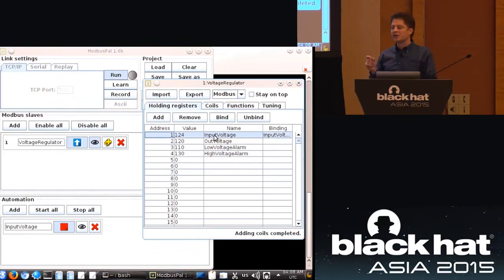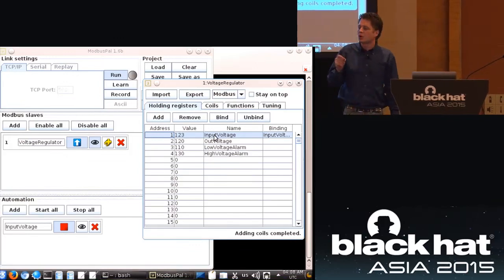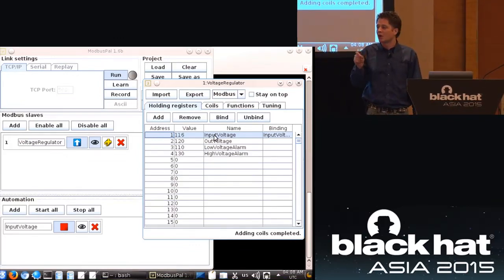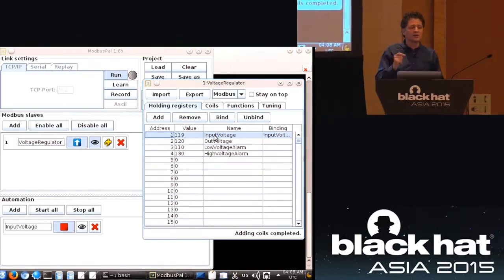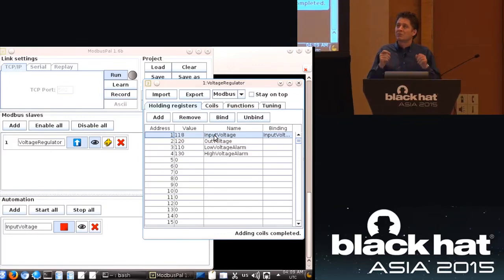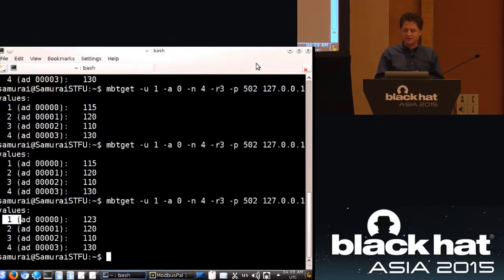Okay? Inside of Modbus, this is a very common thing: the protocol address that we're talking to is almost always 1 digit less than what it's actually listed at on most of the user-friendly screens. So all the operator screens start at 1. I guess it's too confusing to start at 0. I don't know why they started doing that. But the protocol itself actually starts at 0. So I would say 80% of the time that is the case. Every now and again you'll actually have an operator screen or a configuration screen that really does start at 0. So that's something you always have to watch for with Modbus, to make sure that the commands really are the commands that you're thinking that you're sending. Okay? So that's the first thing to it.